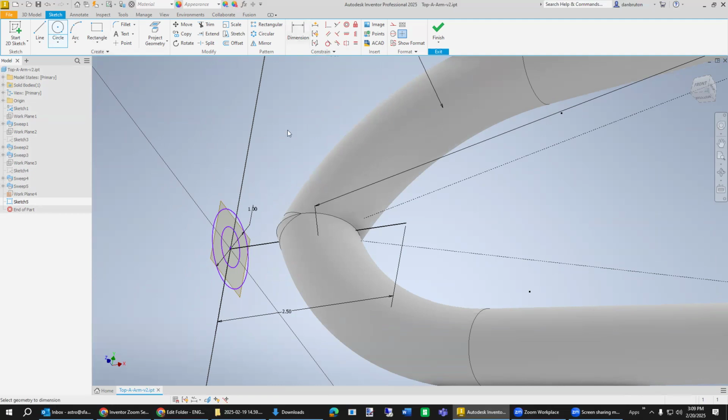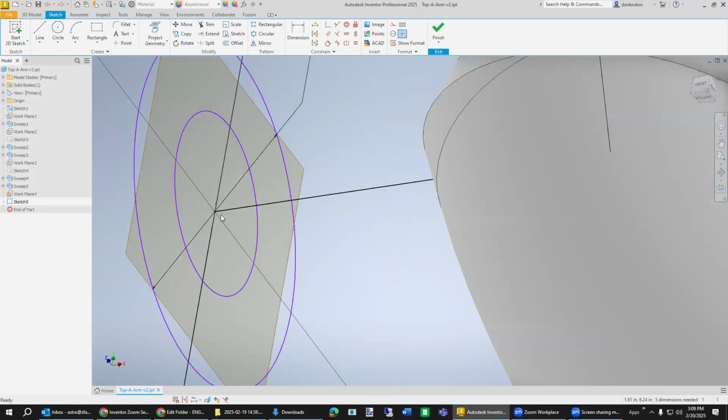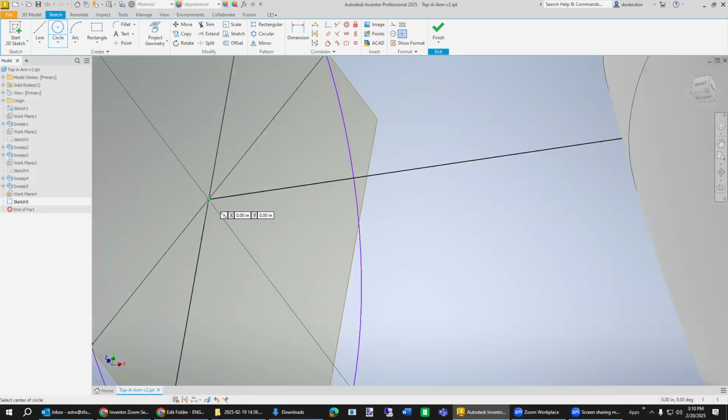And so for this one, I guess I could go in there and do the standard 0.12 wall thickness. And I did not do that right. So I need to do the distance between, oh, look at that. That circle is off. So I need to delete that circle. Should have zoomed in further, right? And coming out to that point, and the distance for the wall thickness, 0.12.